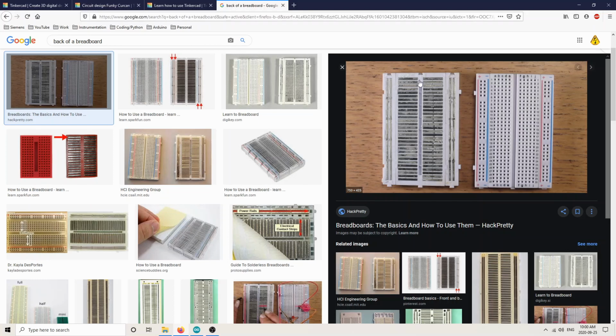So you have a bus that goes right across here. Each of these terminals right here has continuity, and continuity just means that it's the same piece of metal right across. So each of these guys right across has a piece of metal, and then there are two larger bus bars on either side for the positive and the negative, right? Here we can see the positive bus corresponding to this piece of metal right here, and the negative bus right here in the blue corresponding to this guy right here.